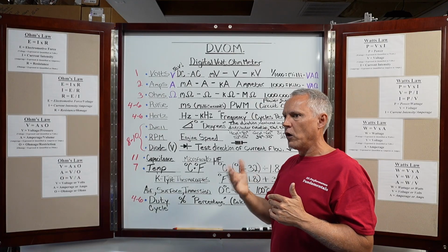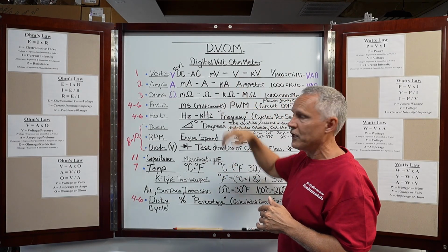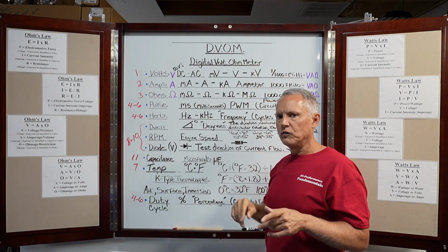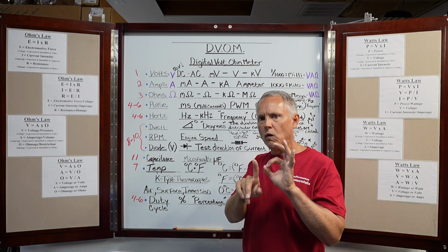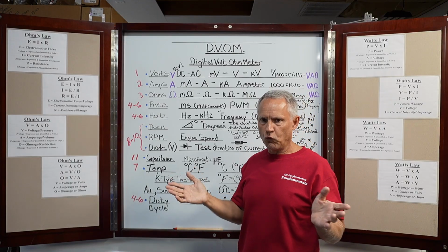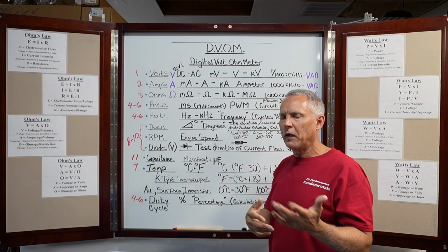If you get into a situation where you're measuring voltage or amperage or even ohmage, and you're on the wrong scale, a lot of times it'll come up like OL. You see OL, it means out of limits. Your scale is wrong. And there may be something else, depending on your meter.